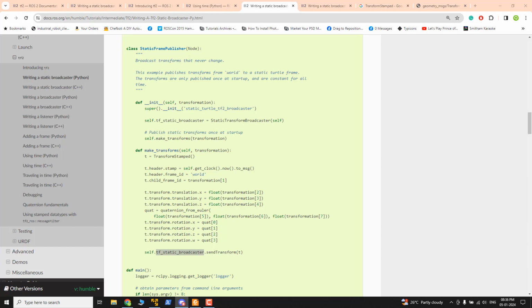While working with an industrial robotics application, we have to publish some static transforms, like for cameras which are not moving at all. So we use the static transform to publish the camera frame. Once we get some data from the camera, we can use this static transform because static transforms are also in the TF tree, so you can compute the camera transform using it.